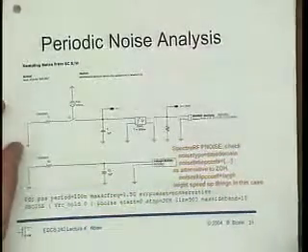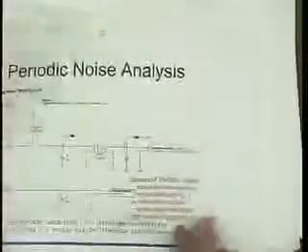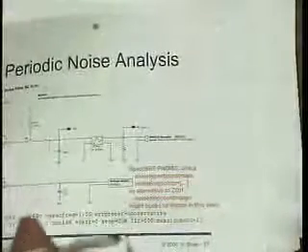Well, whatever. So I wanted to be sure that I can get the right result, and very often I make up some simple kind of test circuit where I know the result from the start. I run that through, and when I'm confident that it is working, then I try it on the big stuff. Trying it first on the big stuff very often is a big waste of time, because it's not going to work, and then you have a big problem on your hands to debug, right?